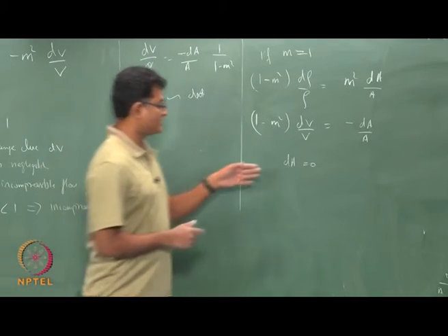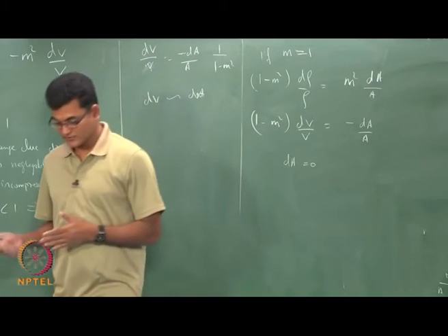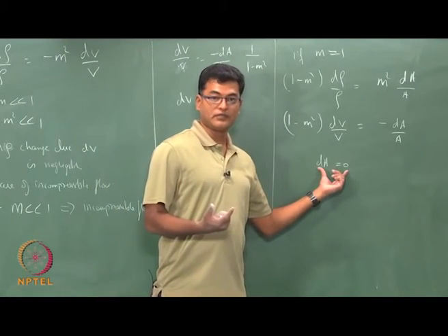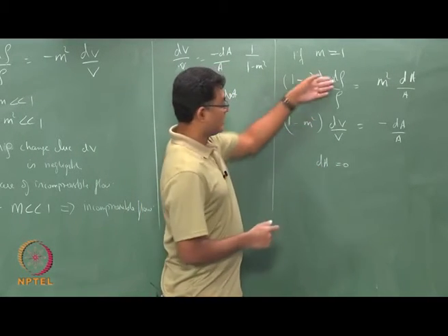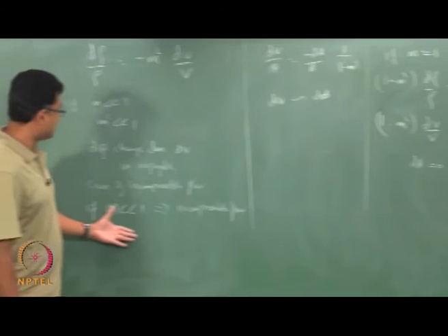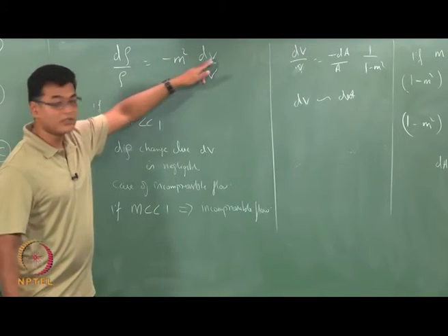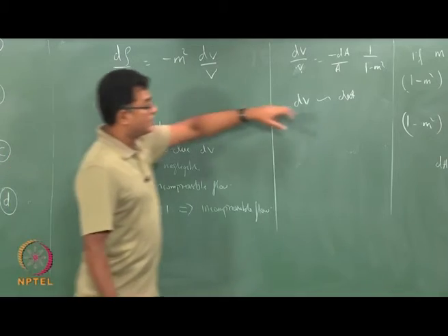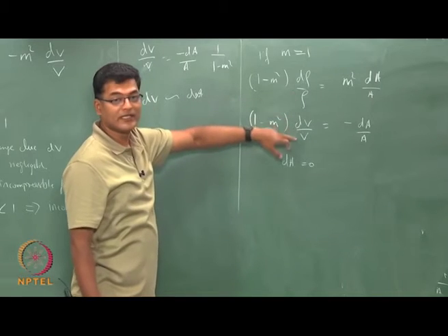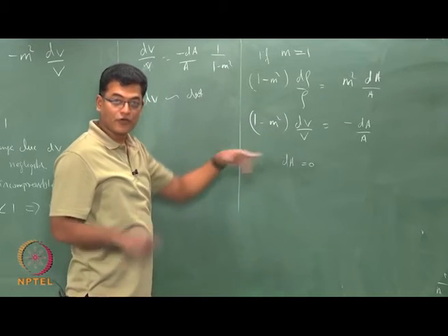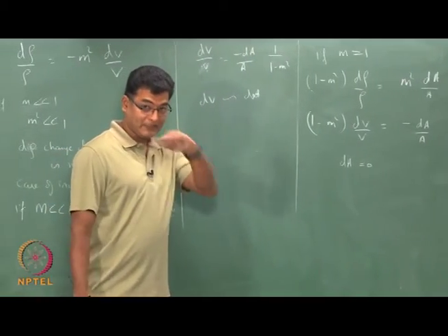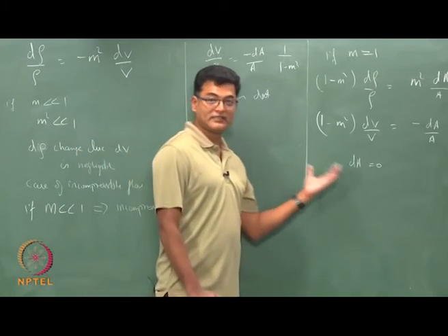That is what we call the throat condition, which we will discuss in a later lecture. So, here the area change is small, so the adjustments are all between velocity and density. So, at very small Mach number, we see the balance is between velocity and area, and at Mach number 1, the balance is between density and V. For all other conditions, it is a balance between density, velocity and area. So, that is the difference between incompressible flow and compressible flow.